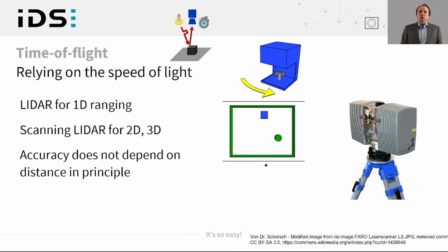Finally, there is one more basic technology used today, and that's time of flight. So what is time of flight? The name says itself that we want to measure the time it takes light to get to an object and be reflected back. So we need to sense time, or we need to sense light travel time. As you can imagine, as light is very fast, this is not an easy task, and it cannot be done by a regular 2D image sensor.